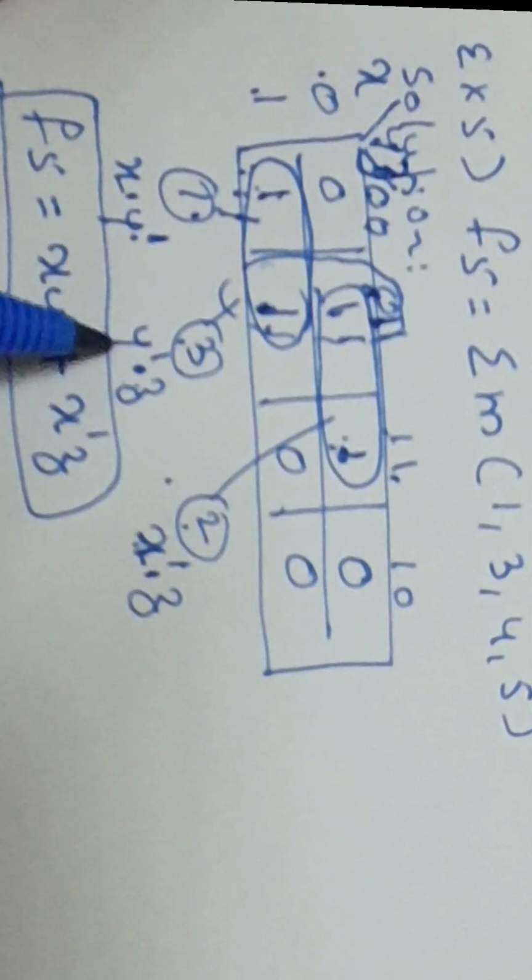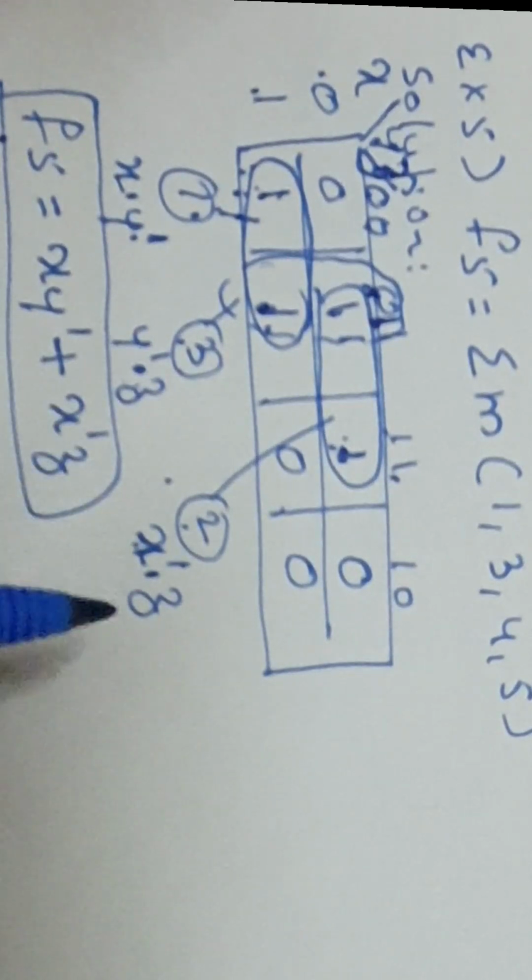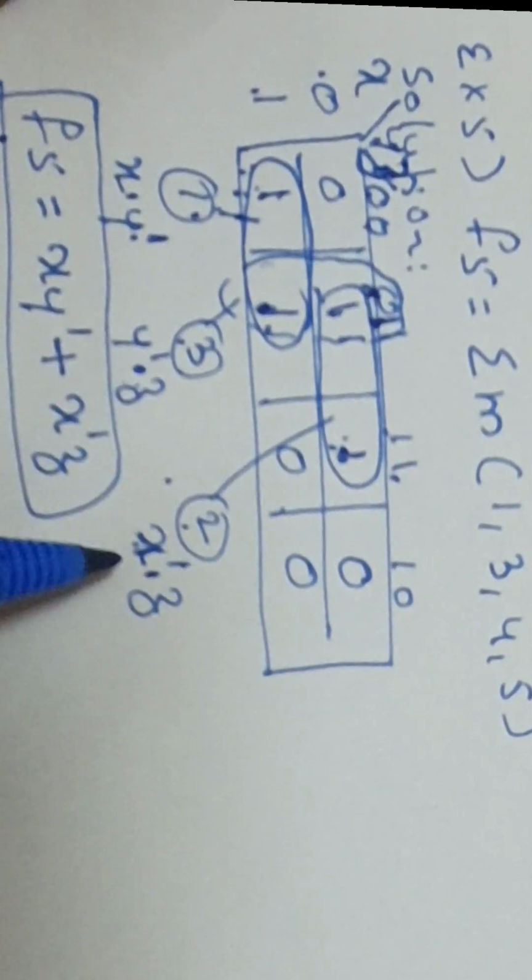Then what is the significance of a redundant prime implicant? Since the members of that group are covered in other groups also, it is redundant. It's of no use. It cannot be written in the final expression. Hence the simplified expression is F = xy' + x'z. Okay, that was example 5.